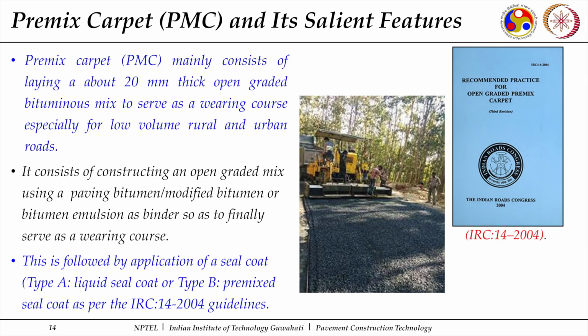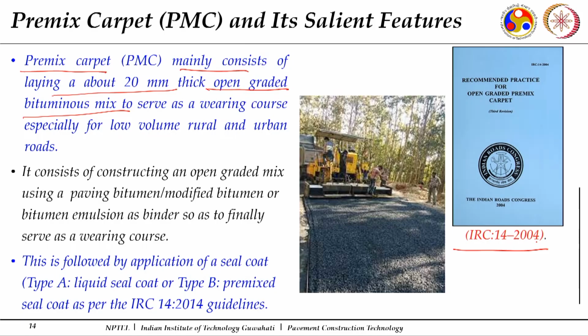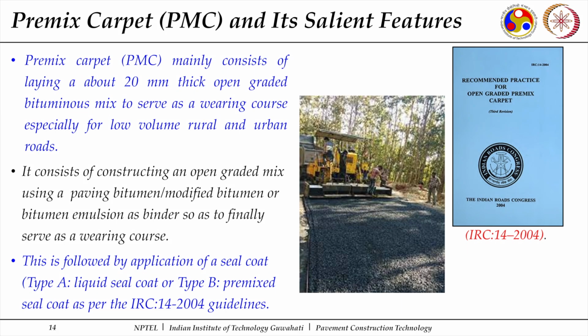Now when this kind of mix is laid, on the top of it we seal the surface. So we will be applying a seal coat to seal this open graded mix from the top, so that water doesn't enter into it. This is explained in IRC 14 2004, the application of premix carpet with the application of seal coats, and two types of seal coats are explained there. So it consists of constructing an open graded mix using a paver.